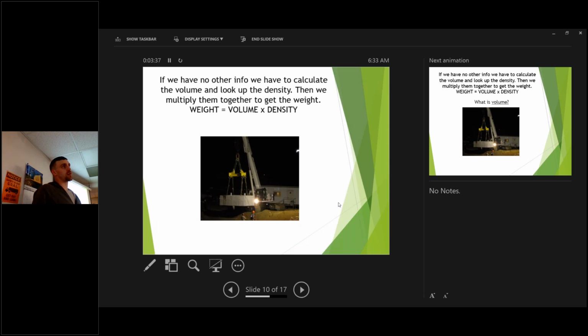When you have something that's got a rectangular cross section, something that's square and regular in shape, you can pretty quickly figure out the volume and multiply it by the density. Some of these densities are really good things to commit to memory. Concrete, 150 pounds per cubic foot. That's a good thing to remember. Softwood, call it 40 pounds per cubic foot. Hardwood, call it 60.